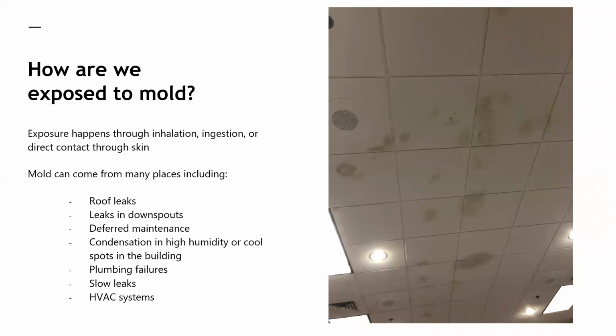So when we think about a school building or a building in general, mold grows because there are conditions in the building that allow it to grow. And that's mainly moisture and a source of food. So if you have moisture problems or moisture intrusion in your building, you're maintaining a condition where mold can grow really quickly. If you smell a musty odor, if that's something being reported, that's usually a clue that there's active mold growth happening in that area. And so you need to take some steps to investigate where the moisture is coming from.